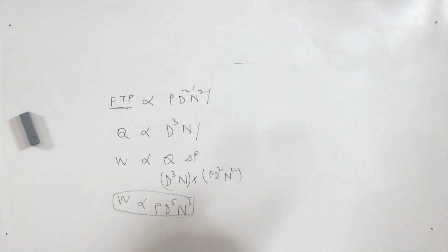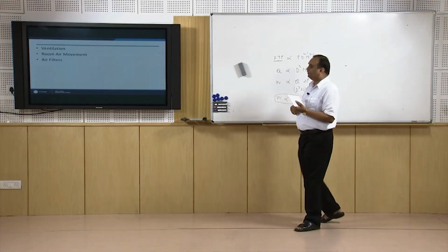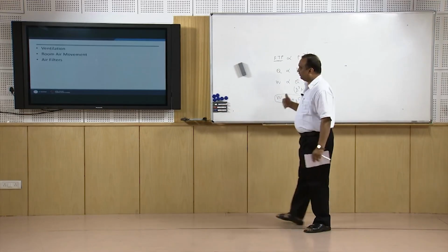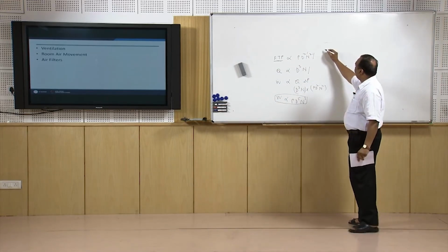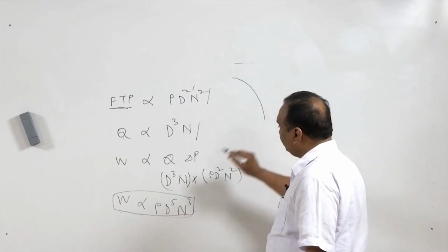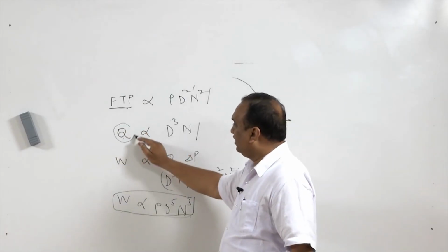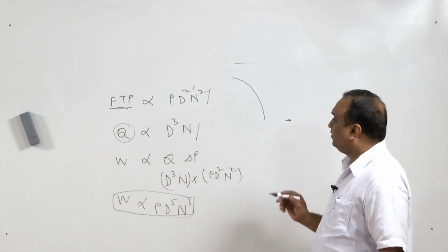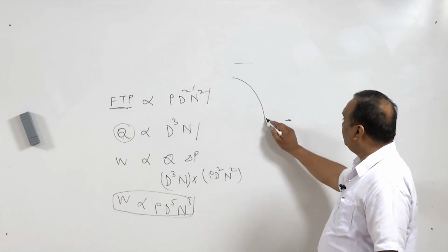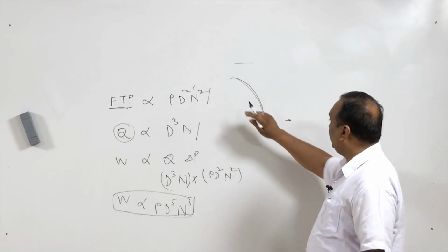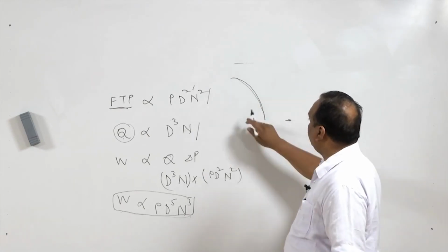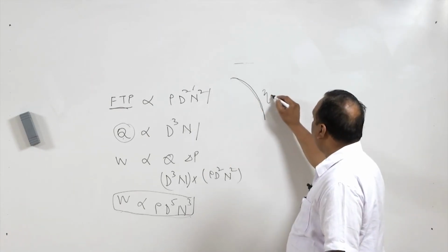And second thing is normally in the fan, suppose there is a centrifugal fan. In a centrifugal fan, normally backward vane type of fans are used, because if there is a flow variation, the enhancement in power consumption will not be significant, and the efficiency of the backward vane type of centrifugal fan is approximately 80%.